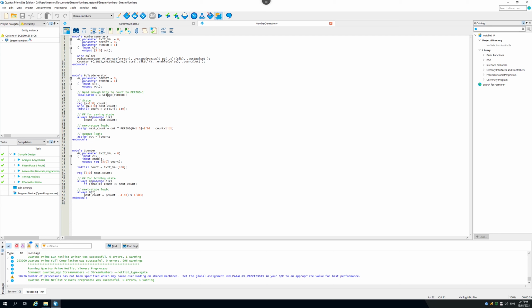So hopefully you know about log2. Because we're storing things in bits, we use 2 to the power of n to know what we can store in n bits. So an n-bit number can store numbers from 0 to 2 to the power of n minus 1. So by using log2, we basically invert that operation. And C says ceiling, it says round up. Not round off, but round up. So this will tell us how many bits we need to store, technically not period, but period minus 1. But I only need to store period minus 1, so that's just perfect.